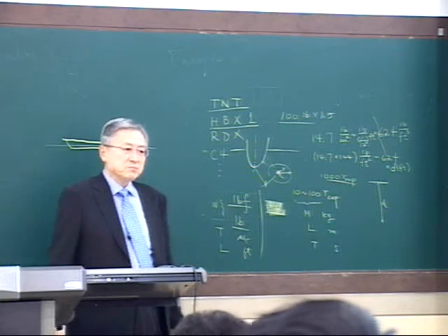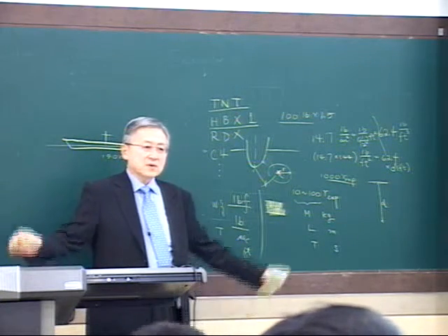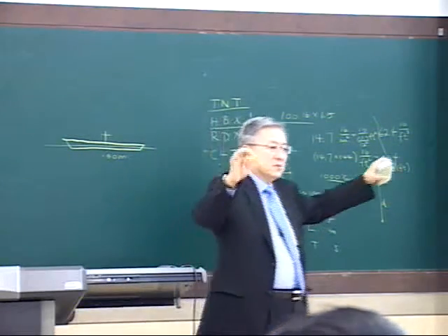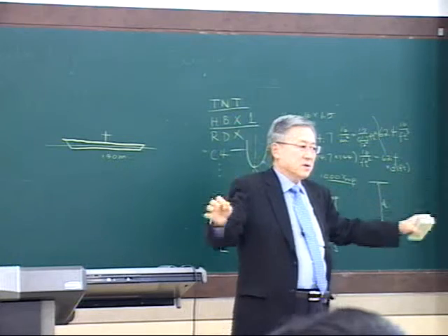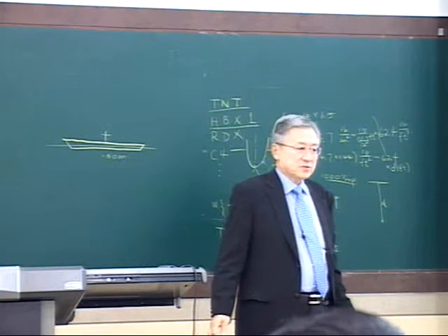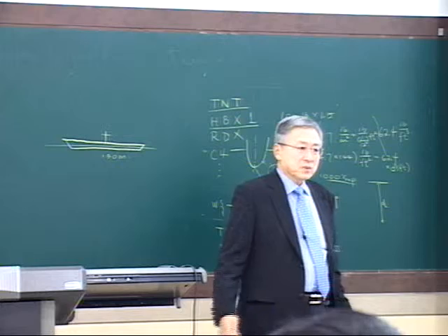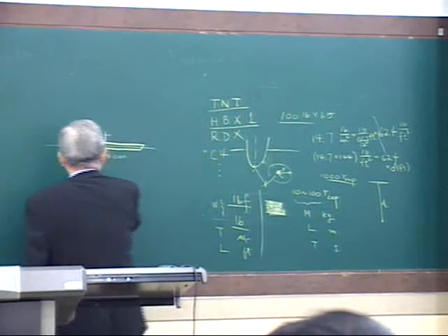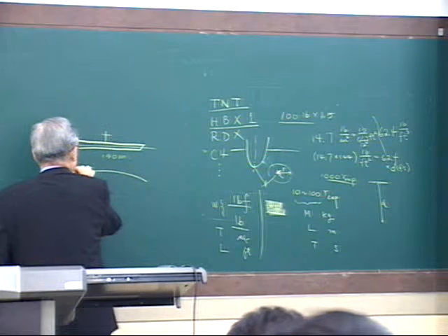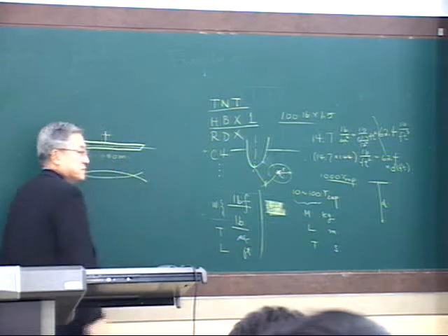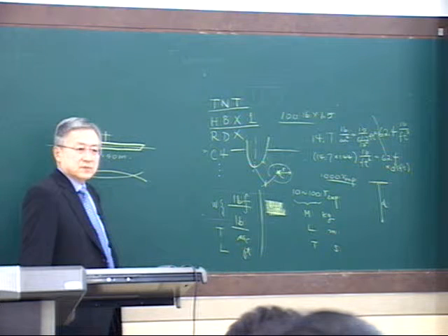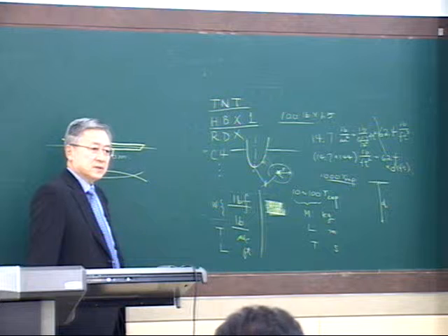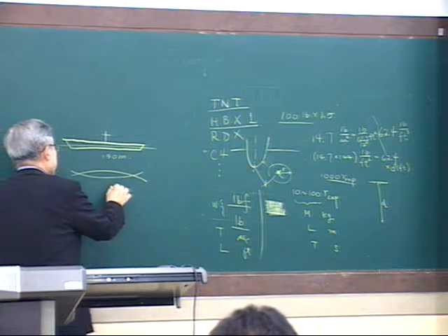Submarine, same beam-like structure. When the vibration occurs, what's the usual mode of vibration? Fundamental mode of vibration, bending mode. It's just the first mode. Flop that way, flop that way. With very low natural frequency. Okay? Let's say 1 hertz.